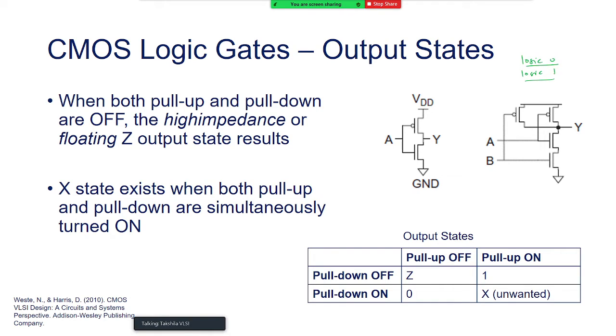And this happens when the transistors are either on or off. So at a time we saw that one transistor is on and the other is off when the logic level is applied, right? What if both pull up and pull down networks are off, no matter whether it's an inverter logic, NAND logic or NOR logic, any logic? Both are switched off.